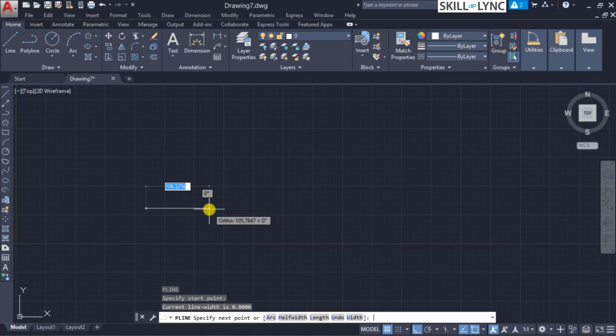That is, you are converting this polyline to the subsequent models that you can generate out of the basic line and arc commands. Next, these 2D polylines can be edited to insert, move or delete the vertices, so that it can be joined to several lines or broken down into its separate constituents. Next, we can also apply the fillet and chamfer commands to these. And also, as discussed earlier, we can turn this into a spline and then also use the curve fitting option in a 2D polyline. That option we'll look into at later stages.